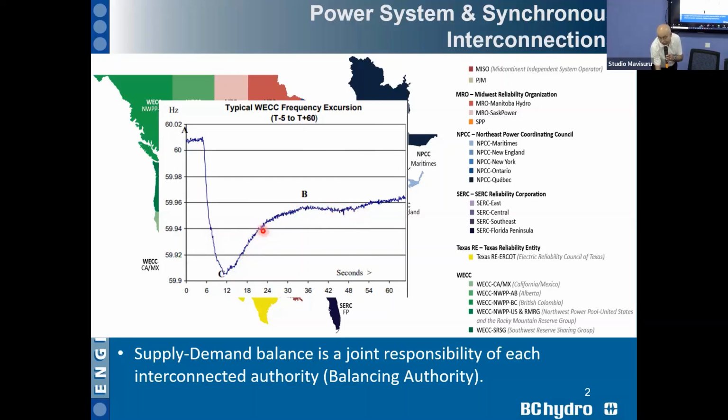Thereafter, we do have one called the AGC computer, automatic generation control computer, which we call secondary control. For any disturbance, we will wait until 20 seconds. After 20 seconds, if the frequency is stabilized, then we know that there's a power deficiency. So then we use selected generating units, we call AGC units. We will send remote raise signals to those particular selected generators. Those generators are selected based on their spinning capacity, how many megawatts they can take more, as well as the water in the reservoir.